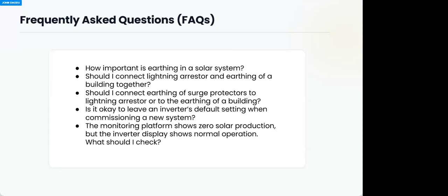You will be advised and have more knowledge. And from that moment, when you see it in another inverter, because they may not name it the same way in different brands of inverter. I mean, in one inverter, it may be termed low battery cutoff. In another place, they may term it battery disconnect point or something. So you need to understand every detail about the equipment before you start changing. That's the best. So that's my own advice concerning that.